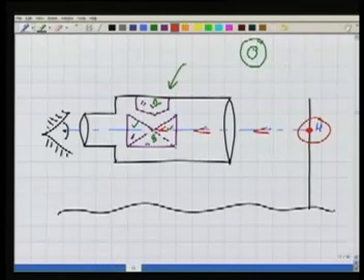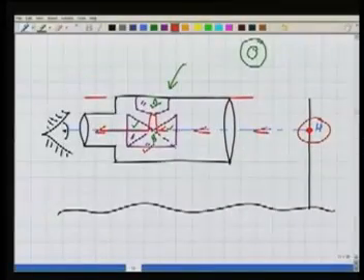From B it gets reflected, and through this optical train it comes back and follows the same path as the blue line, while this level is horizontal. This is the case when the level was horizontal. So in the case of the horizontal, this will not make any difference. It will just change the route of the line of sight, which will come like this, go to A and then go to the eye.